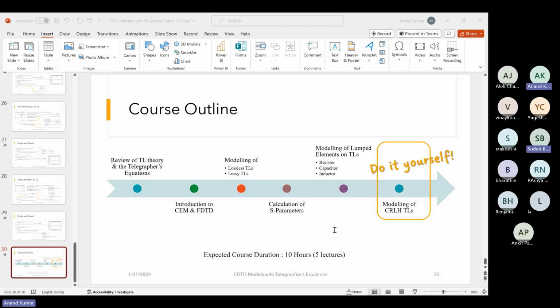I have not encountered any standard meshing algorithms for FDTD, since FDTD is actually a meshless technique, so we don't actually mesh it. We divide the entire simulation space into cubes and then assign the permittivity values. Most FDTD codes are actually home written. Scholars and researchers write their own codes and use their own way of filling those dielectrics inside the matrices.